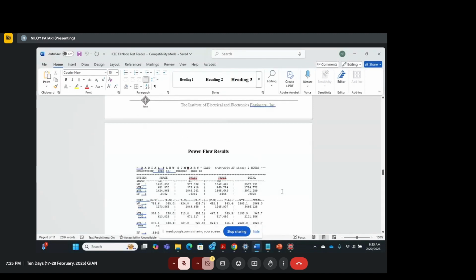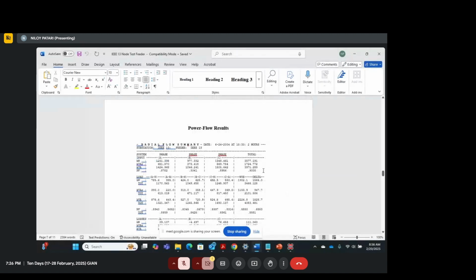then you'll get these power flow results. Now, whenever you do any kind of research work or any kind of modeling, and you have a standard IEEE test case with power flow results, you have to match your model results with those power flow results. Then only you can say that your model is validated. So if you have an OpenDSS model of the 13-bus system and you take exactly the line configurations, the same exact connections and everything, R and X values and everything, and at the end of the day, if you can't reproduce the same power flow results as given here, then you cannot validate your model, right?